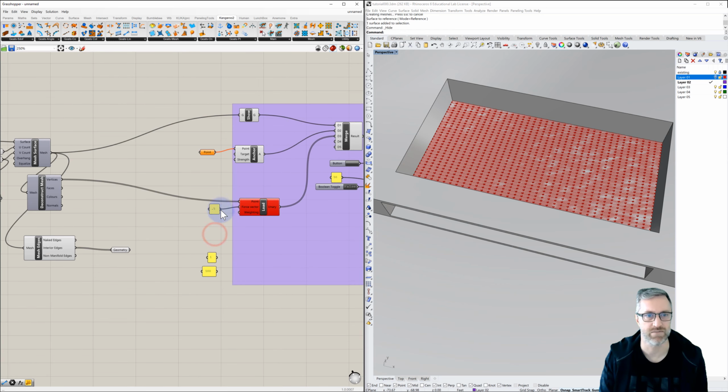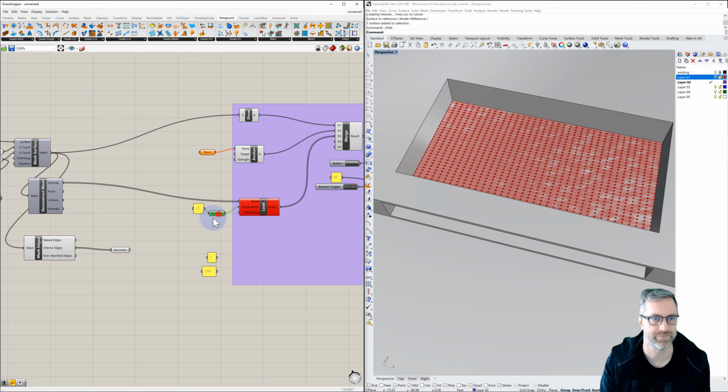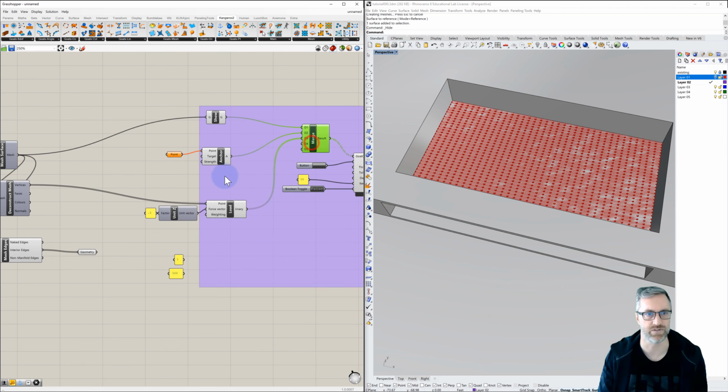And let's figure out what it's not liking. From text to vector. Interesting. Sometimes these accept it and sometimes they don't. Unless that's not the problem. I see the problem. It's not the number, it's that it's a vector. And so we need to set this as z. So it'll be positive 0.5 in the z direction. And now that accepts that, and that moves through to there.